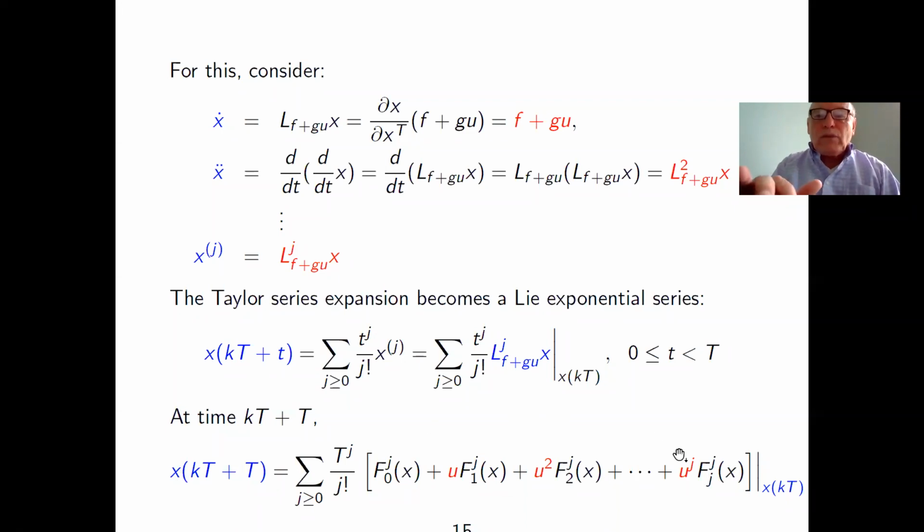So the lesson from here is that it is very complex to do exact discretization of nonlinear systems. Even though the structure that we need is still preserved in this expansion, the actual state and the given control input produce the next state in a highly nonlinear fashion.